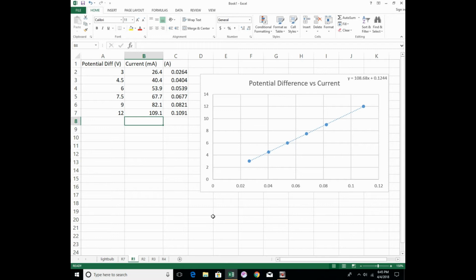Particularly for these, they're usually plus or minus 5%. So they're supposed to be anywhere from 95 to about 105. And so this one seems a little outside of that. We might go through and I can double check my measurements. Maybe some of my equipment is off. Or maybe the resistors have been damaged a little bit from some of the things that we've put them through over the years. That being said, we're still pretty close in the ballpark. We're at about 109, so we're about 10% above.